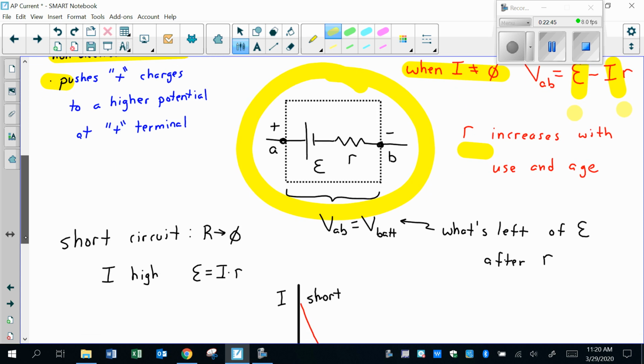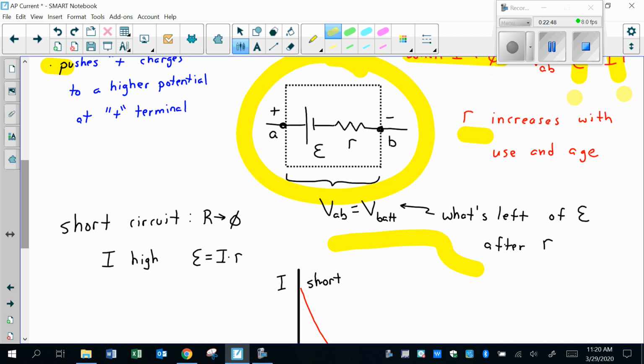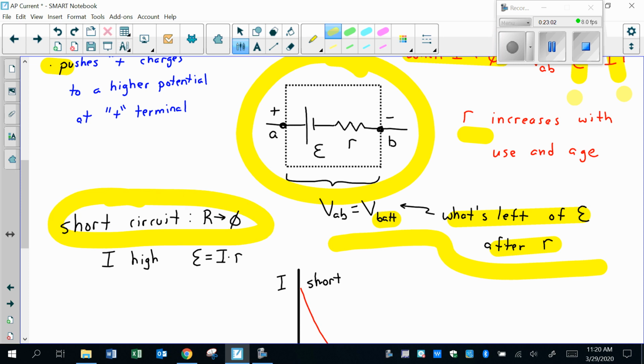So in moving down here, just another way of explaining everything. The voltage of the battery itself that we are getting is what's left after we lose some. Now we have this term over here called the short circuit. Short circuit is basically where you have a circuit that offers very little to no resistance. So usually it means that your device, your light bulb or whatever it is, somewhere wires got switched around and it's basically not being used. The current's able to bypass that light. Current's always going to take the easiest route, so if there's a route that goes around the device that's going to use up that charge, then it's going to go that way.